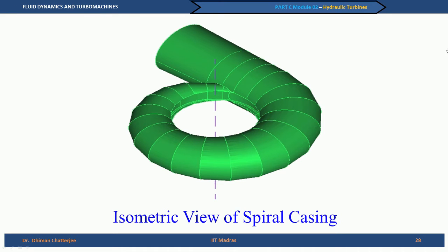Why is that? It is because a portion of the water leaves. So, initially there is a V dot volume of water entering the spiral casing from the penstock. Now, V dot theta is the volume of water that will come out at any angular location theta. So, the volume of water handled by the remaining portion of the spiral casing reduces, and in order to keep the mean velocity constant, so that the mean velocity going to all the blades will be the same, we need a reduction in area. If you recollect the discussion on pumps, this is just the opposite.